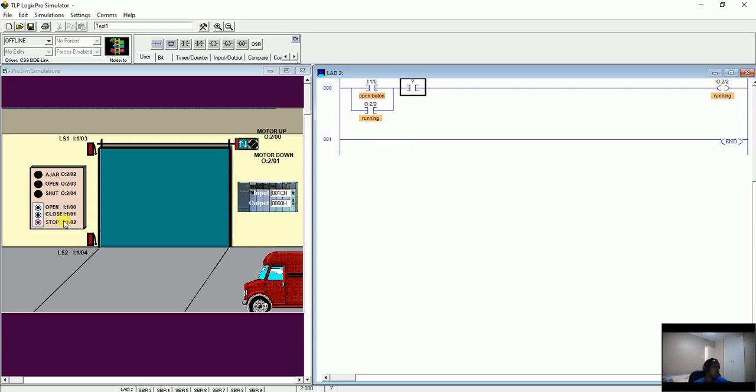Here it's actually our stop. This is the one that we're going to use to stop. It's going to be my stop button. Remember, it's normally closed, and as soon as we go online, the PLC is going to detect the 24 volts, and it's going to change the state to closed. So I hope you understand why I have used this contact. It's examine if closed, because we're only watching for the closing signal. The contact in the field is closed.